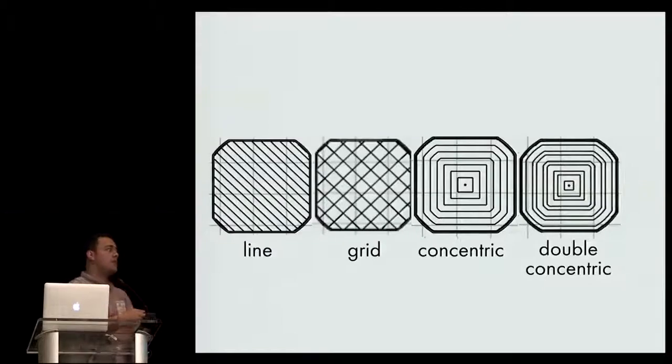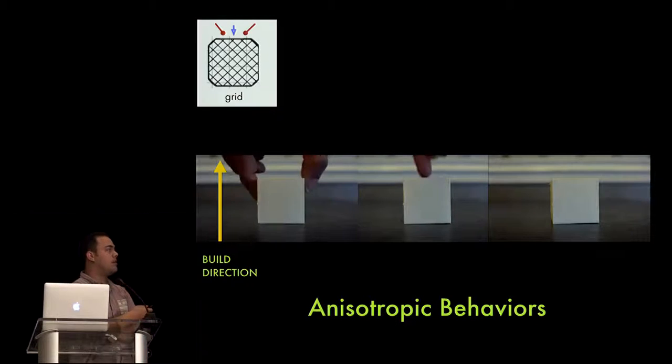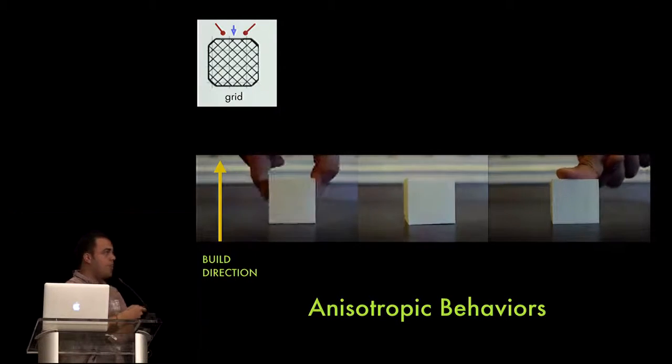In order to achieve this, we looked at controlling or designing a couple of new infills for 3D prints. Infill is usually just used as a support structure, so that you don't have to print an object completely solid. But in this case, we leverage it with the thermoplastic elastomer in order to leverage different types of compliance.